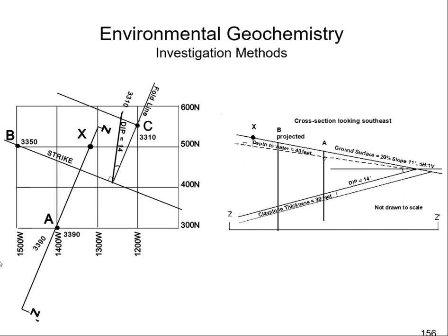And if you do that and it asks what the strike and dip is going to be, you're going to get a mirror image for the strike and dip. And it will be the wrong answer, and it will be an answer that's provided. So just be careful with that. Northerly numbers increase to the north, westerly numbers increase to the west, southerly numbers increase to the south, and it's the easterly numbers that increase to the east along the x-axis. So we have located our points on here in the coordinate system once we've laid it out properly.